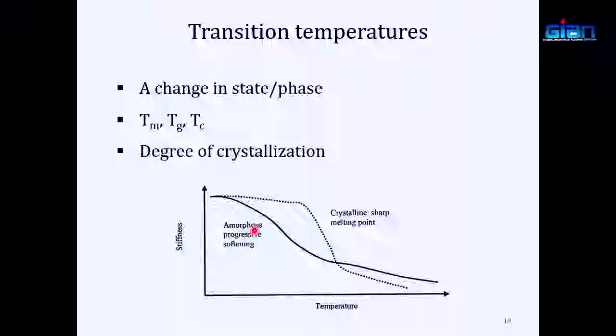But when a polymer melts, it has become a low viscosity liquid. But if you have plastic, which appears to be solid at room temperature, if you provide some heat, slowly you will see it becomes soft, then it becomes a very high viscosity, extremely high viscosity liquid, and then slowly you would see that the viscosity is going down, getting thinner and thinner as you increase the temperature. So there is no sudden change like in crystalline material.